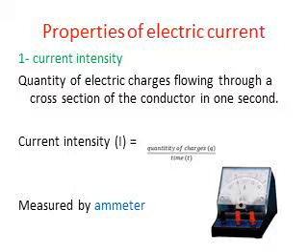How can we calculate the electric current intensity that's passing through a certain circuit? By connecting a device called an ammeter, and this ammeter is connected in series, as we connect the negative line of the ammeter with the negative of the circuit and the positive with the positive, as a part of the circuit to measure the current intensity of this circuit.